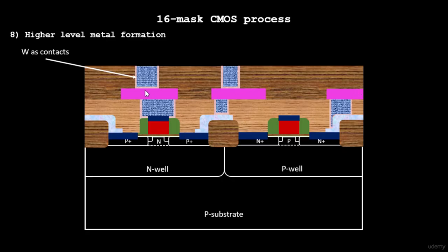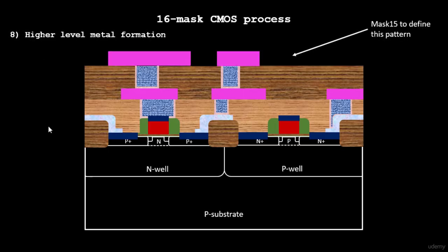Let's say this is just an example. We can have various combinations of that. So let's say we want these three sections of the contacts to be coming out of your chip. So what we do is we create a mask 11. Now we remove the mask from the structure, and we have the photoresist present over here. Now we'll etch off the extra titanium nitride we have.